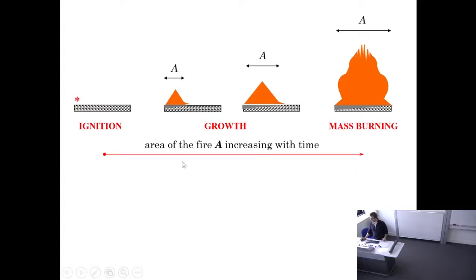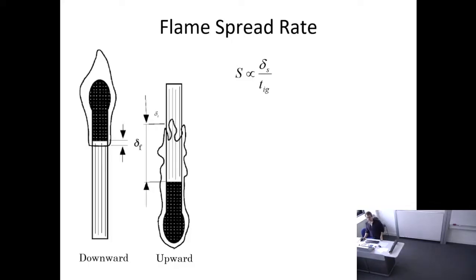So you have a fuel layer, you have ignition, there is a flame that establishes itself, and what happens is there is a continuous movement of this flame forward because a fraction of the heat from this flame is heating the next layer and the next layer and next layer. What you have is the process of growth by the specific form of flame spread, which happens to be an absolutely fascinating phenomenon. It's just not the ignition and the flame spread. Flame spread can be thought, as I said already, as a succession of ignition events.